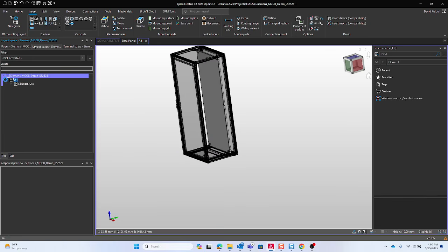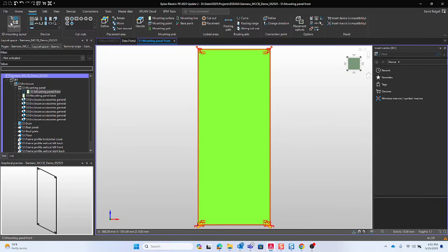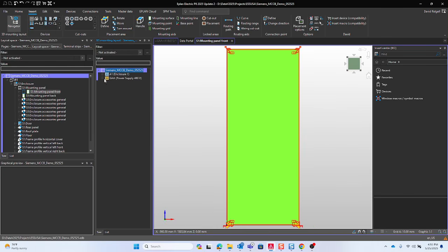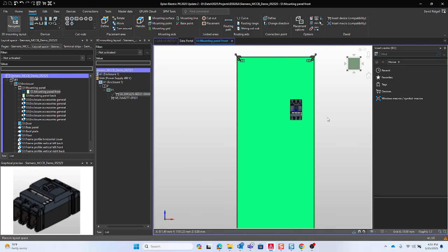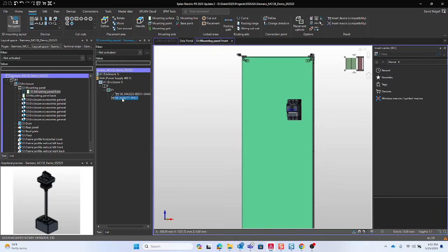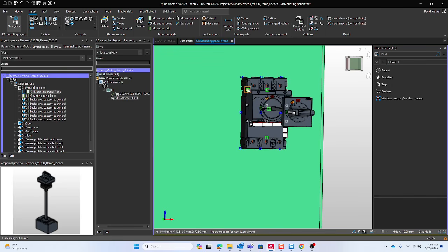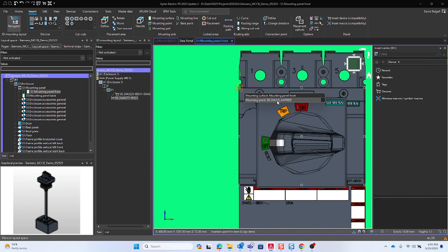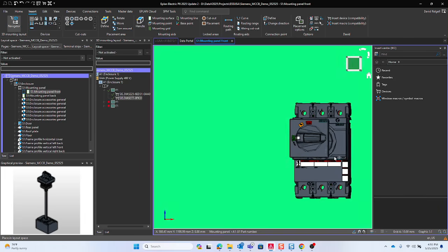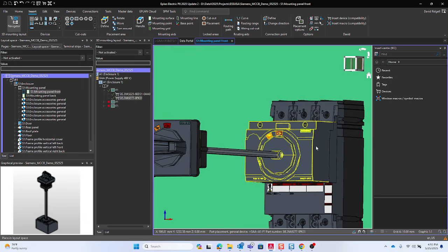Okay. We will activate the mounting panel front, and then turn on the 3D mounting layout navigator, and we'll place this breaker. Okay, that's good. Let's place, or at least attempt to place, this guy here. We can see, let me just line it up from the front. We can see there is a mounting point for this, so as far as this mechanism here, it mounts perfectly fine.